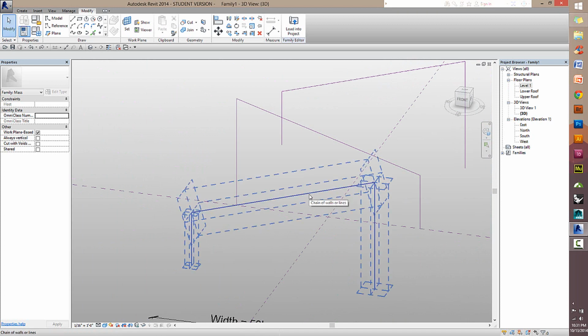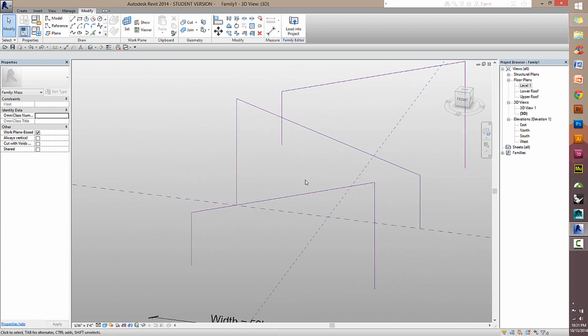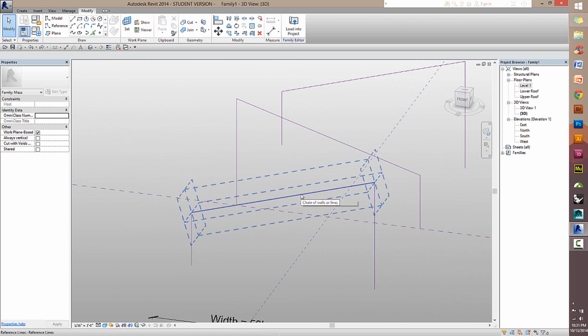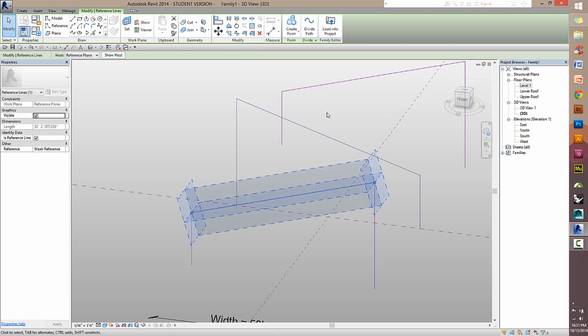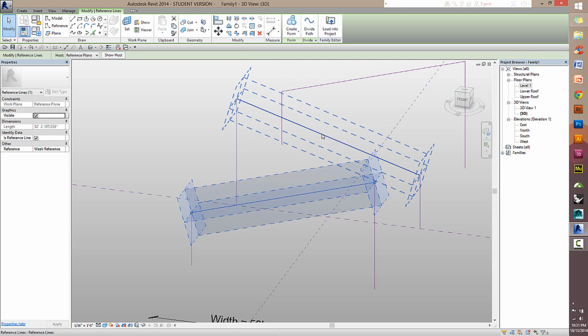This time, instead of just selecting the object, I'm going to mouse over it like this, then hit Tab. Tab cycles through the selection options that are currently available to your mouse's position. So it made it switch from selecting the entire chain to just one segment. And I'll do the same here.